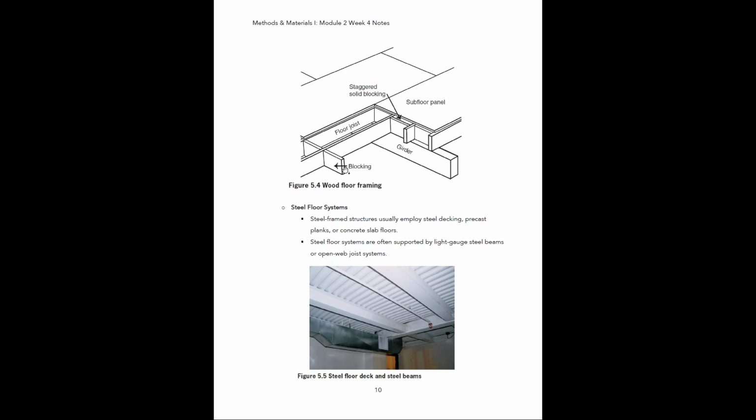The purpose of these is to tie the joists together so that basically the entire load of the floor system is all tied together at that point. And that will prevent the floor joists from getting deflection. Deflection is basically that bowing shape in the top of them as weight is applied. These being tied together just offer a greater level of support.